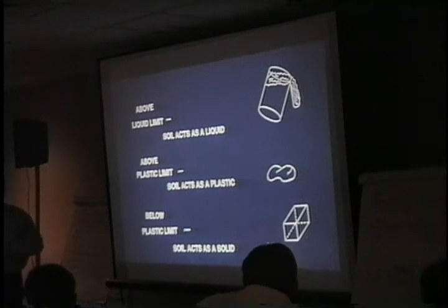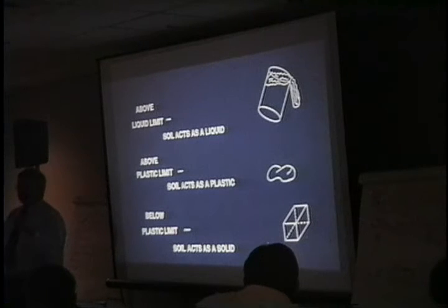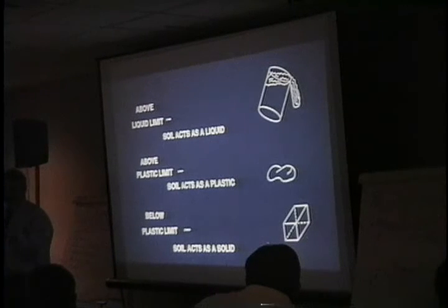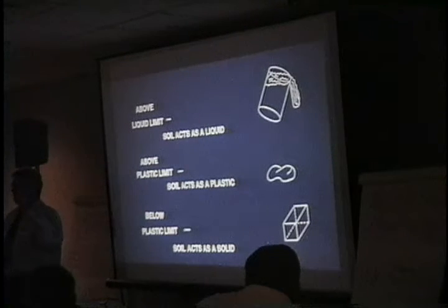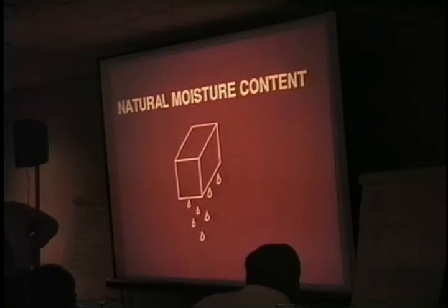And, you know, the experienced person can pick this stuff up and just run it through your hands, make a little 1/8 inch roll, bite it between your teeth. You can tell a lot about it. Don't swallow when you try it. Natural moisture content is kind of an oxymoron.